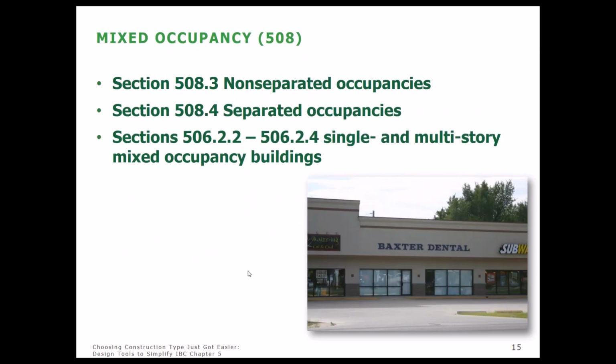There are a couple different approaches for mixed occupancies. I'm just going to remind us of the basic principle in the code that if you have 2 occupancies or 3 occupancies, you look at the more restrictive one, and if the entire building can fit into the limits of area and height for the most restrictive, you're good to go. Design its size based on that most restrictive occupancy.